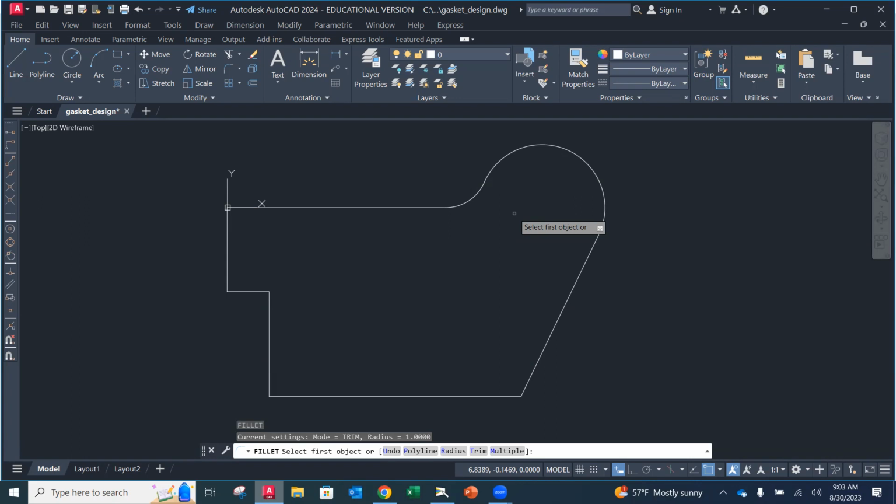So I'm back in the fillet command, and this time I want to put that radius of 1/4 inch in here. But the last one that I set was 1 inch, so I know I have to go back to the radius. Right now it would do a 1 inch one, and I need to change that value to 0.25, enter. Now I'm going to select this line and that line, and it puts it in for me and ends the command. I've got one more fillet to put in. Press the space bar. It acts like the enter key and it remembers the last command.